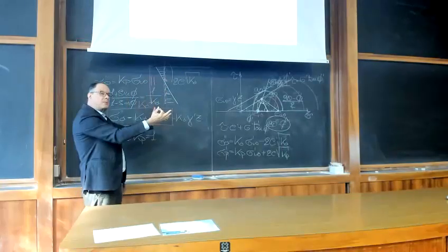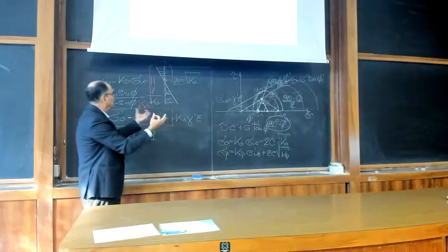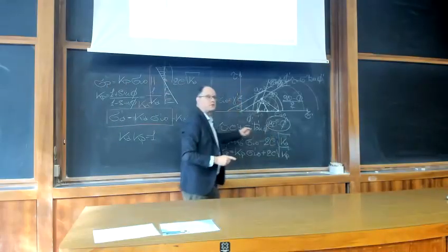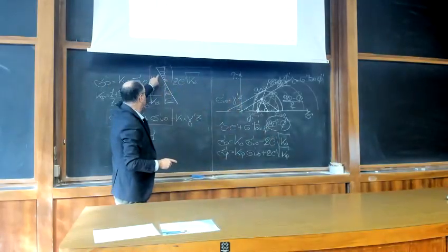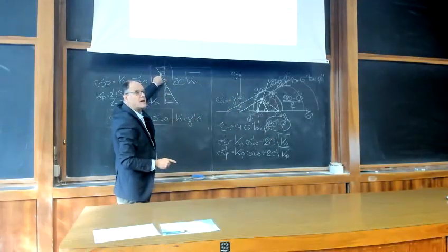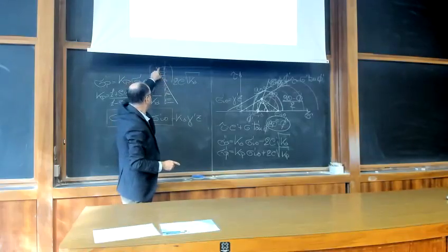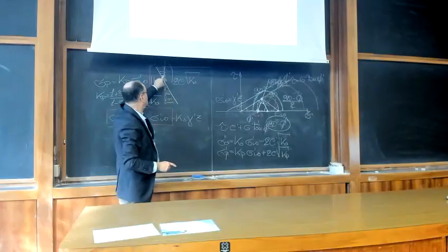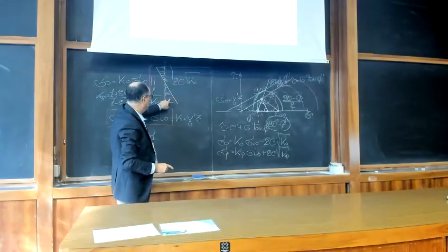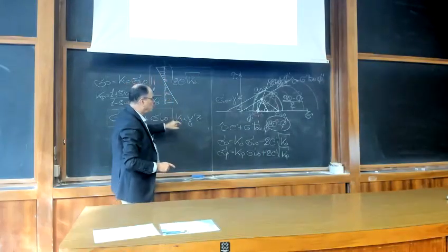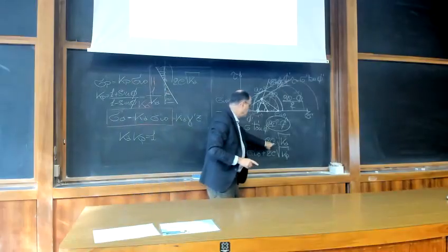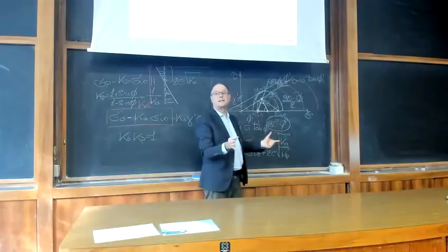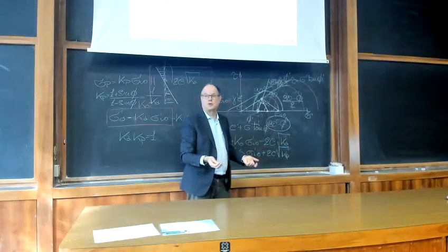So everything is somehow translated by this constant value. And of course, this is a better situation, because if you consider that this is negative, and if you make the integral of this plot, you find the resultant, you will see that in presence of cohesion, the overall active pressure is less than for a cohesionless soil.